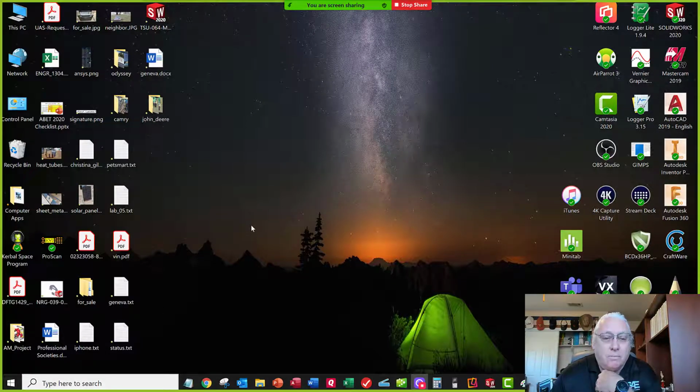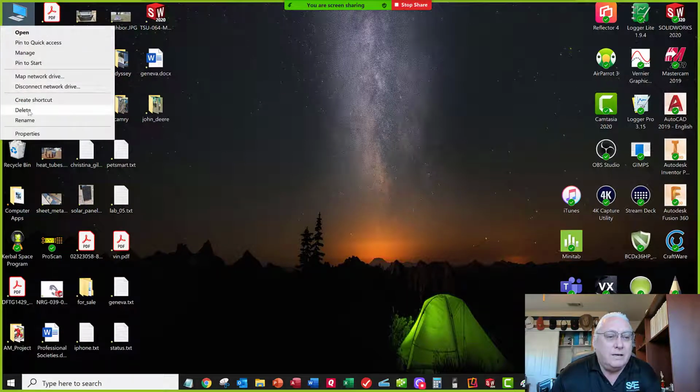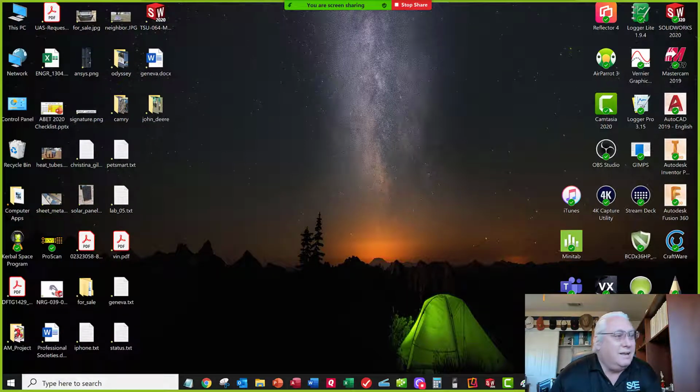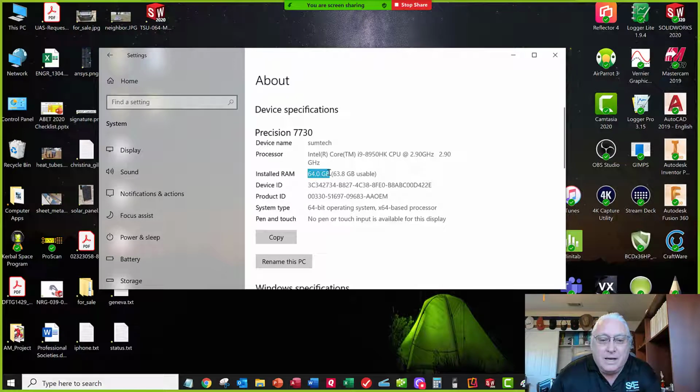First thing, with computer memory, I've had students ask me about SolidWorks not running on their computer, their educational version that they've downloaded. And so what you need to do is go to your settings. I'm going to right click on my PC here on the desktop and go to properties. And you'll get a listing of your computer memory. And on my computer, I've got 64 gigabytes of installed RAM. And some students have as low as 8 gigabytes, even less than that sometimes.